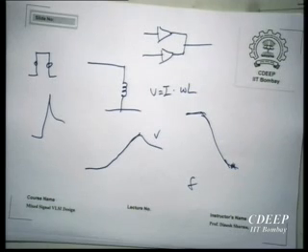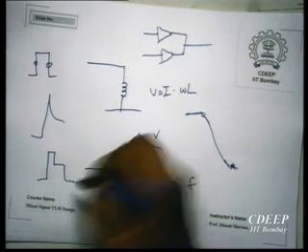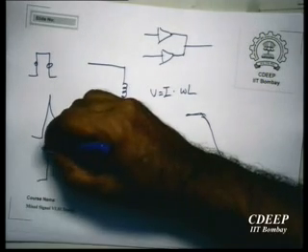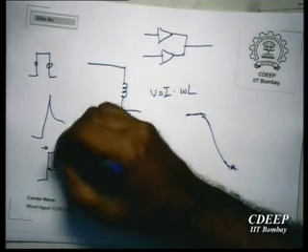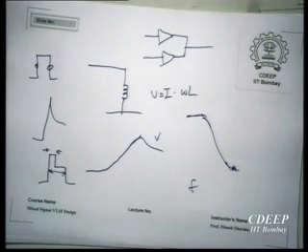So in short, the digital equivalent of that is that when I want a square wave, I'll actually drive it like this. I will turn on my high current driver for a very short amount of time and the other guy for the full amount of time. Therefore, for this much time I'll get the sum of two currents, and at the other I will get only the average current, right? So if now this current is low and this is quite high, then I will not spend too much power, right?